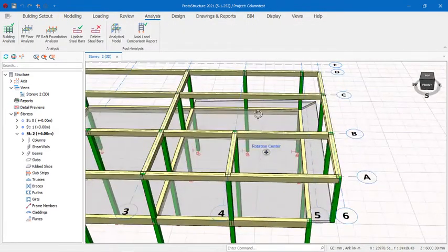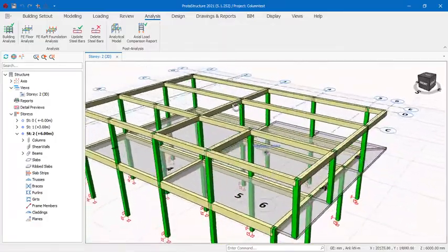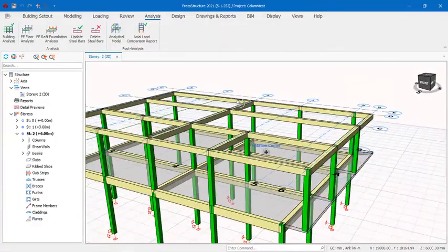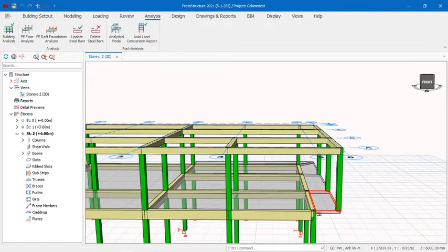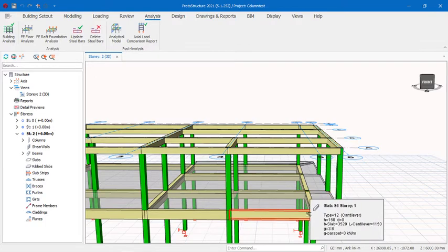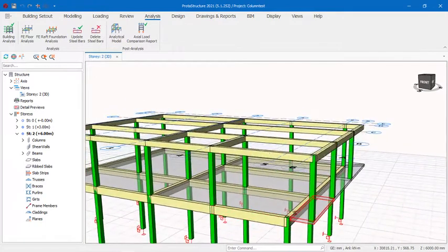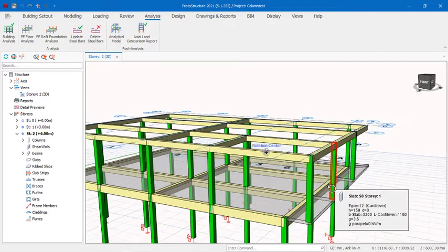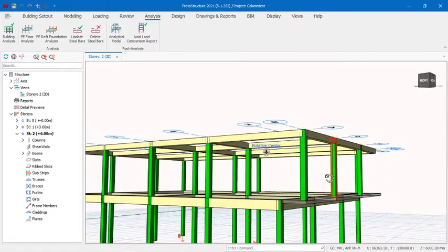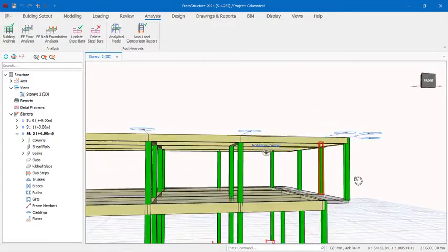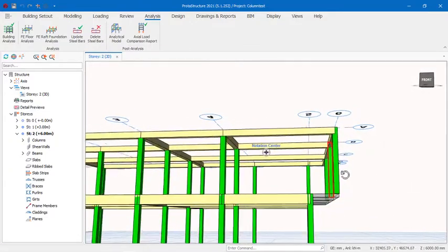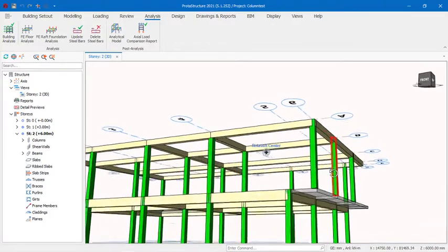Okay, so this is the arrangement, and I've done the analysis, and you can see the result that it is bringing. Now, another thing some engineers do, which also works anyway, is that they will provide beams along the edges to support this slab, so that it will support this column. But aesthetically, for some architectural designs, that might not fit well into the architectural concept of the building.